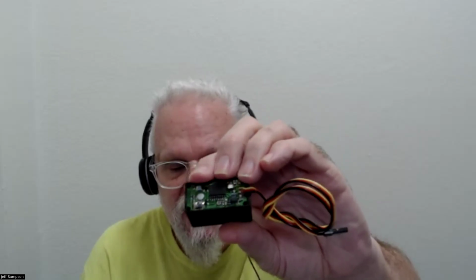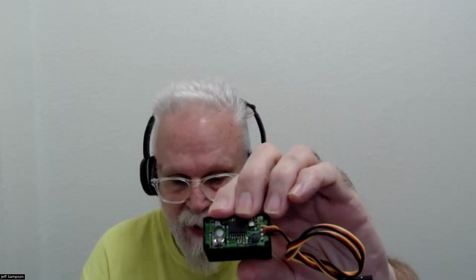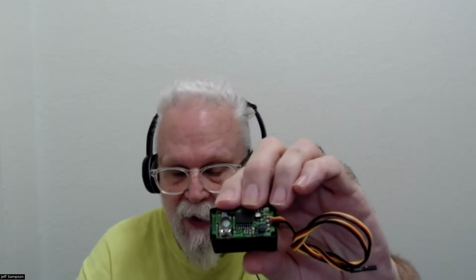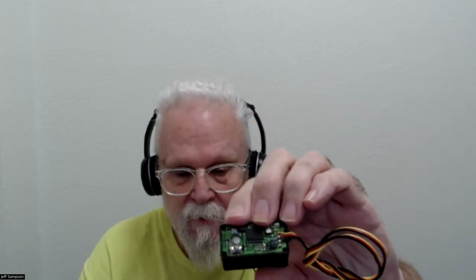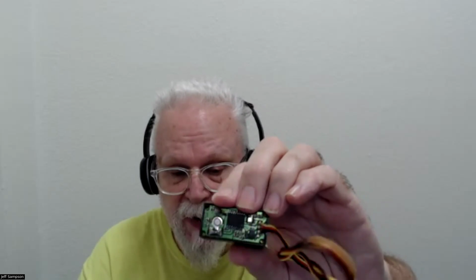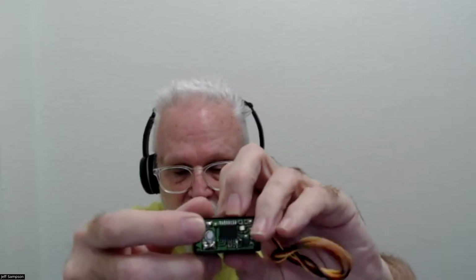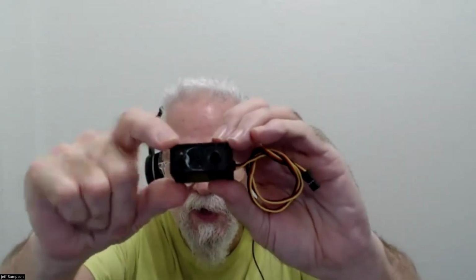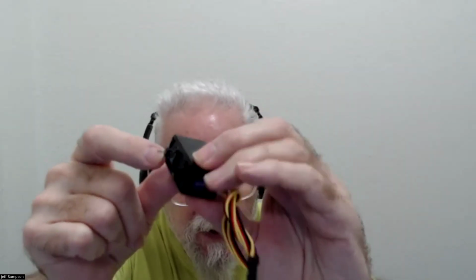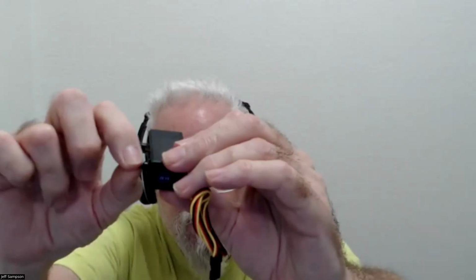And then the thing is, when you first do this, you hook it up and put it on something with a reference, either like Bob's doing, say put out the 50% PWM, which should center it, or if you have a radio control transmitter with spring return to 0, just leave it at 0. And when you turn it on, the motor is going to be turning one way or the other. So then you have to grab the pot on the board. And again, it's just a kind of double D shaft sticking up. Yep, there it is.